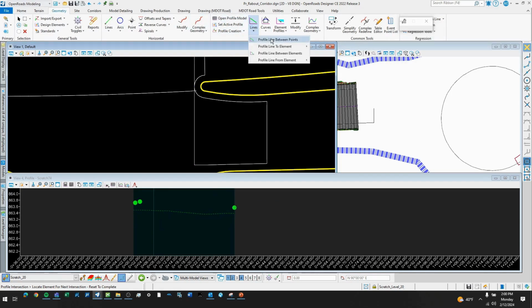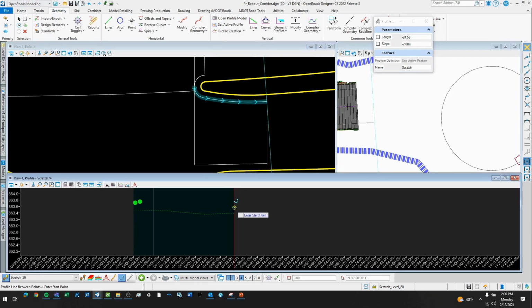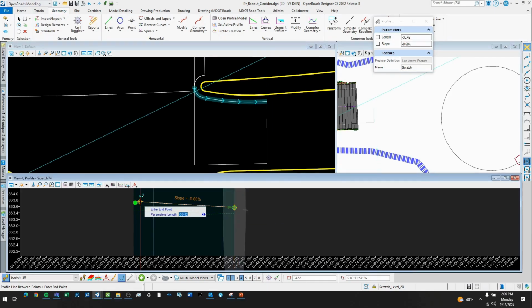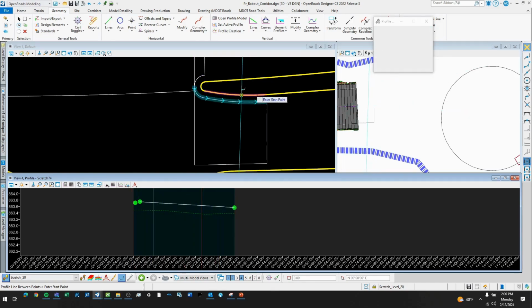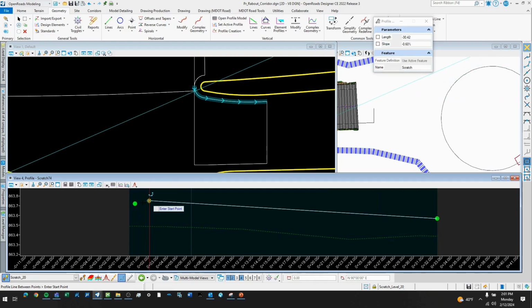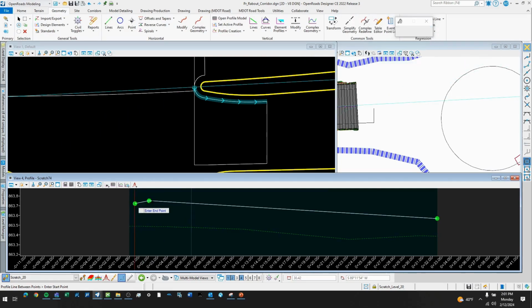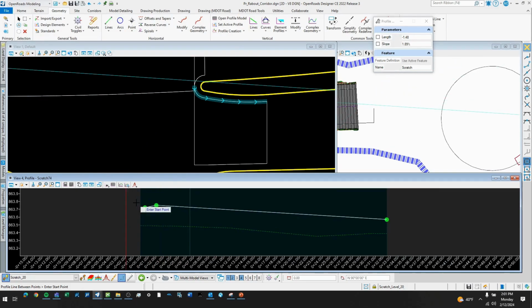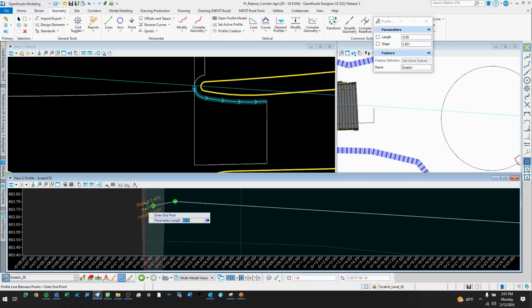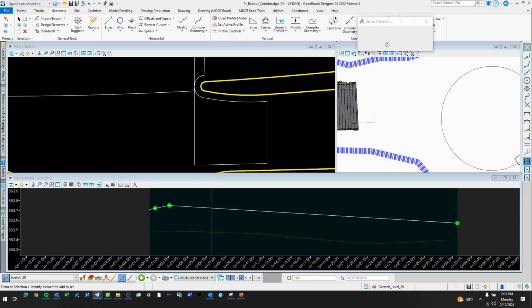And now we can map these out together, so we know it wants to go from here, over. You can see this is at 0.6, so with that curvature in it, it's never going to be the same. This one's going to be a lot closer to that 0.3 that we had, but this one changes. And then we'll connect those two down, and then really this is just going to continue. This is pretty much perpendicular, so I'm going to keep this going at that 2% slope and just end it there, and that way we have a tie-in point for that side.